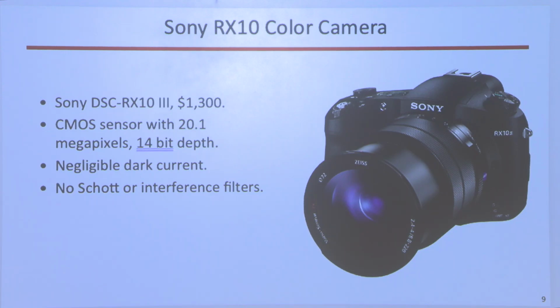Another way you could use this camera, as I mentioned, if you had a nice steady laminar flame, is to put a line filter in front of this, say at 450 nanometers. And so then you take a picture of the flame at exactly 450 nanometers, pull that off, put on another line filter, maybe at 650, take another picture. It's really an excellent way to measure soot temperatures or smoldering temperatures.